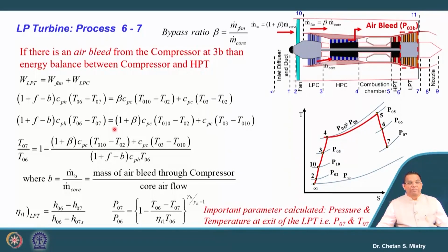Okay. So, we need to be very careful here in terms of doing all the calculation when we are having the bleeding case. We will solve the numerical also, that will give you confidence in terms of consideration of the air bleed. Here you may have a question, say sir, suppose 2 to 5% of air we are taking from, say, the HP compressor, and that is being used for cooling of the HP turbine. So, be careful, under that configuration this mass balance will be retained. Whatever has been lost from the HP compressor will be gained here, and for the LP turbine it will be similar.